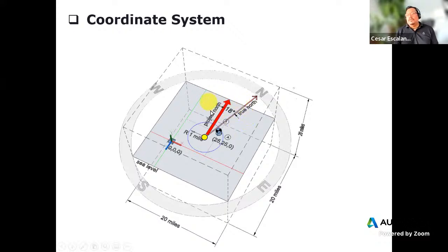This information is something you will get from the civil drawing or from any record document of the existing site. It's important to use as many decimals as you can, because an error in orientation of a decimal, particularly in a very large site, can translate into important dimensional distance, in particular when the point is far, far away from the project.